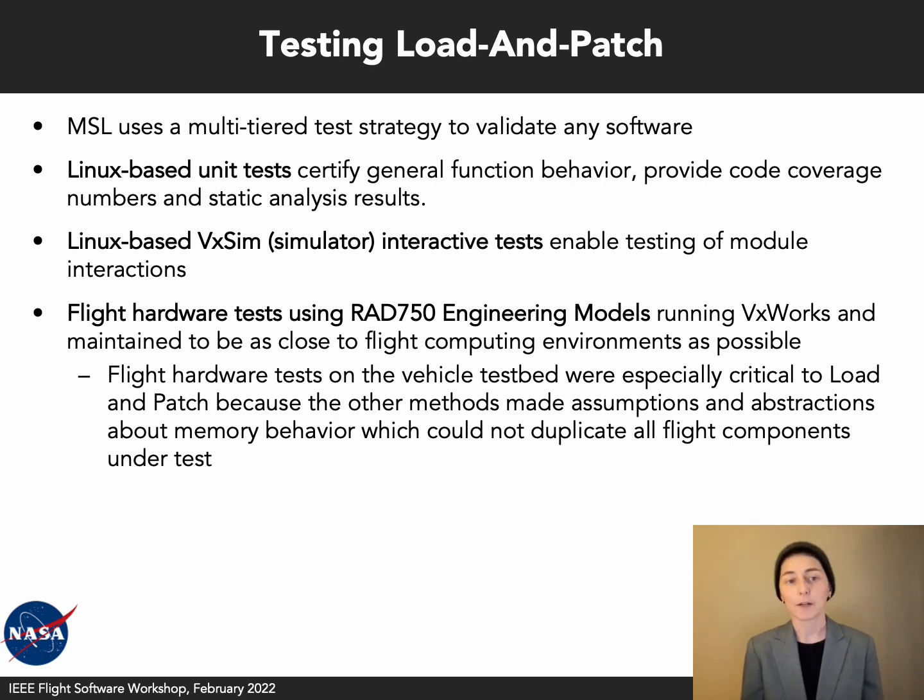Finally, we have flight hardware tests using the RAD750 engineering models, running VxWorks and maintained to be as close to flight hardware as possible. And this was especially important because all of these other methods make assumptions and abstractions that are just not true. Specifically, the VxSim has different endianness than the RAD750 engineering model. So it was really important to get onto the hardware.